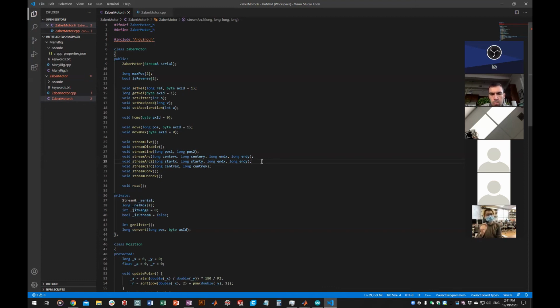But if you change that, there will be a mismatch between the specified locations and the actual physical locations after you change your task parameters. Then if the system tries to use the arc, you'll crash it. The only way to resolve that problem is to do a home and then restart everything.